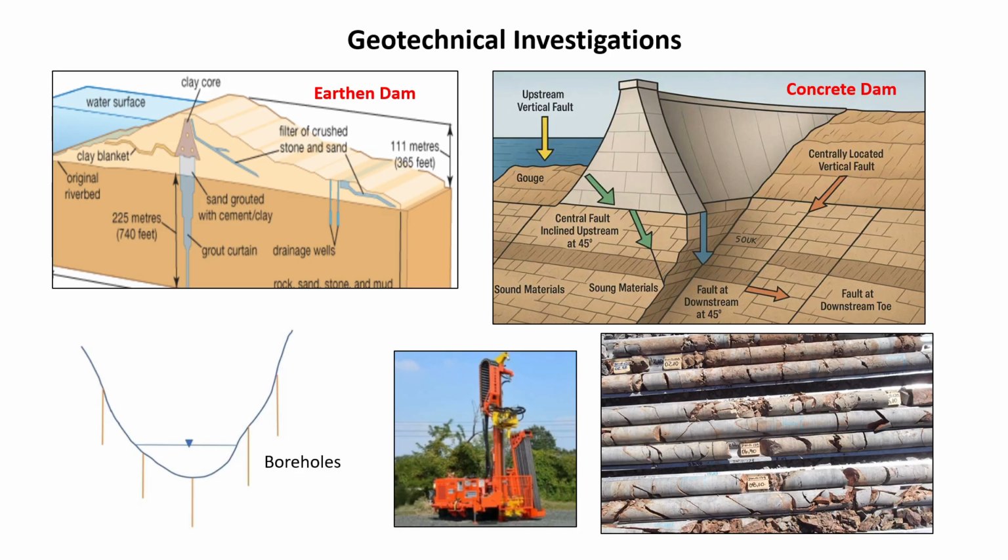in the foundation. As you can see in the above images, earthen dam as we are placing on disturbed or soil foundation, there are chances of seepage. To stop the seepage, the blue color extended to bottom is known as grout curtain. This will stop the seepage from upstream to downstream. It acts just like the core in center of earthen dam.